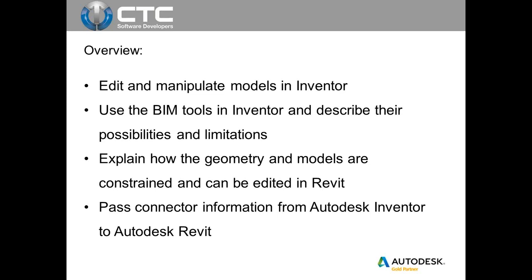Now there was one drawback to this process in the sense that when you export it out from Inventor, you would just get a 3D block in Revit, and the process of exporting itself would involve simplifying the model. When you simplify the model, there are certain pieces of the element that get deleted that are not really in the user's control. So you may have to do some more modeling inside Revit before you can actually use it in your projects. So they've taken a very big step in that process and made things a little smoother now. There are limitations, which we'll see as we go along.